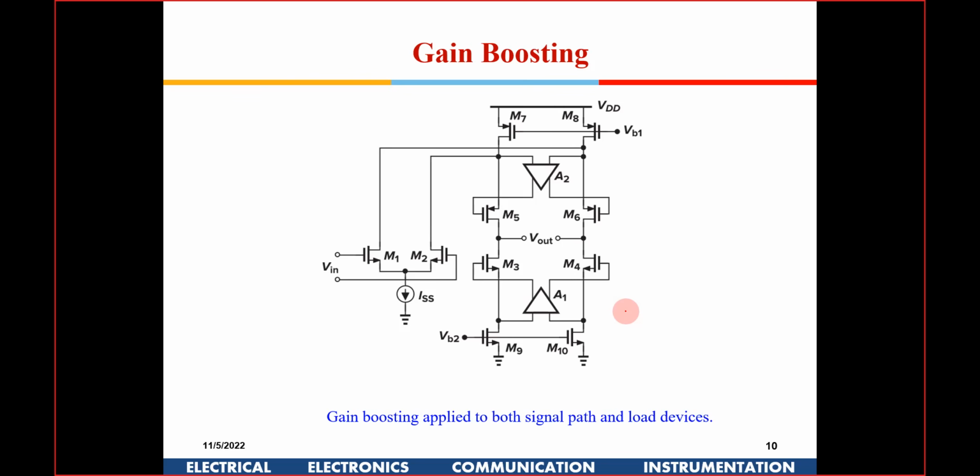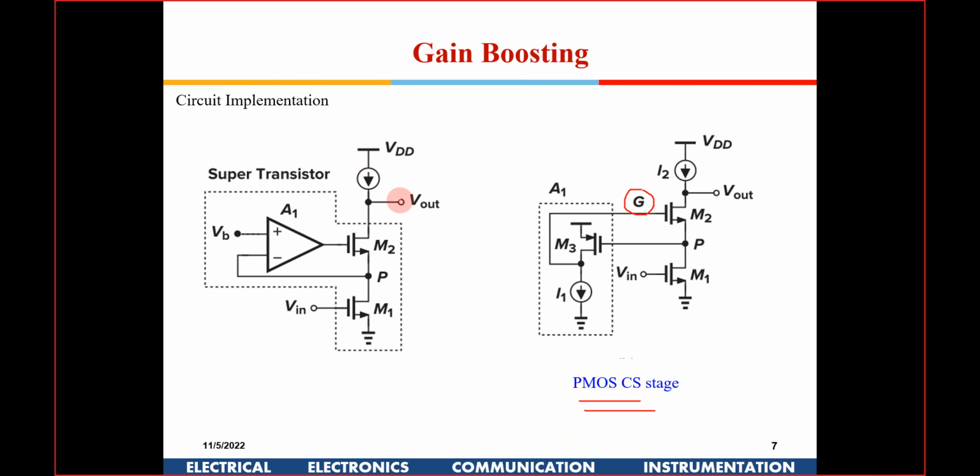Now in all these cases, if I go back here, I am just talking about when I look from the top, the resistance is much higher. But after doing all these things, if instead of this current source I put just a normal current source, the resistance as seen into the top will be much lesser, right? Then that will become a dominant thing. So whatever we have done in the bottom needs to be done in the top side also. Only then you get a very high gain. Is it understood what I am saying here?